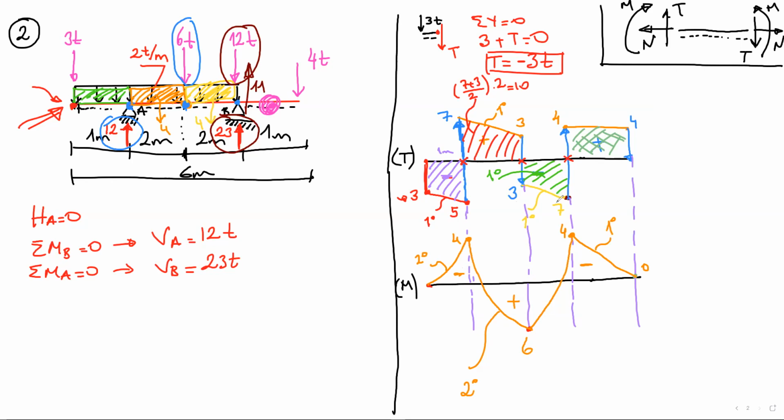Okay, let's have a look at the system. Here, we have 3 critical locations, and at these critical locations, you can see a minimum moment at the negative side and a maximum moment here. So when the shear force diagram goes through 0, it's a critical location for my moment diagram. We should take these critical points into account.